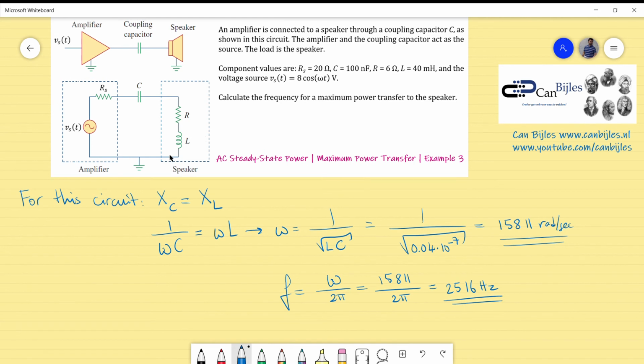If you increase the frequency, let's make it, for example, 1 gigahertz, very large, what will happen to the circuit? The capacitor will behave as a short circuit because 1 over omega times C, with omega very large, is in practical situations very low, so let's assume it is 0, so this is actually a short circuit.